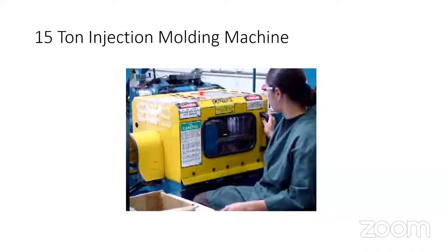If I give you one parameter and you apply the same parameter, it is not good. You have to go through the material: engineering plastics, commodity plastics, specialty plastics, high-tech plastics. There is not a single type, and therefore the parameters keep changing as per the melting point and the molecular weight of the polymer.